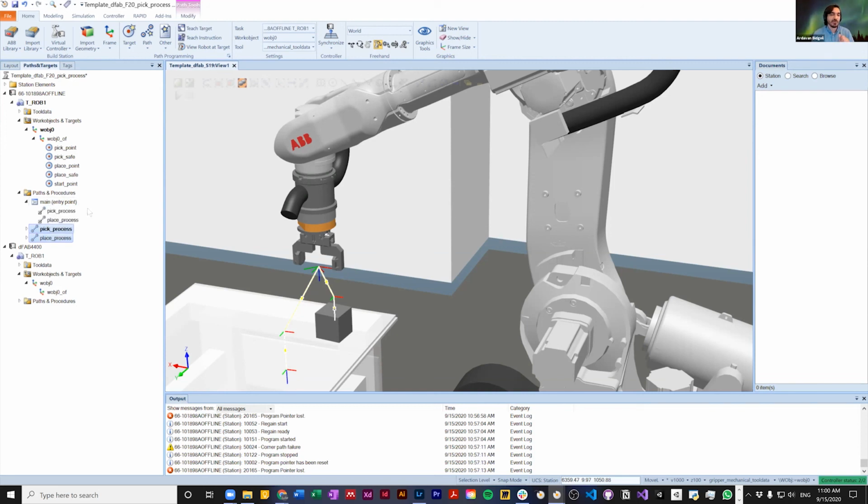And you may ask yourself, what is this main thing? How does it show up there? The point is, main is the default procedure that the robot looks at whenever it wants to run. So when you generate a rapid code and you hit run, the robot only looks at the main procedure and nothing else. If you have copied your codes into this main procedure, they are going to run. If not, they're just going to be there without any special use.